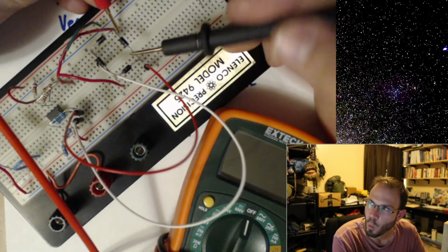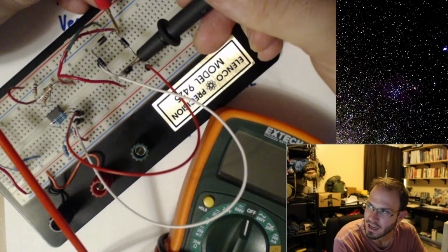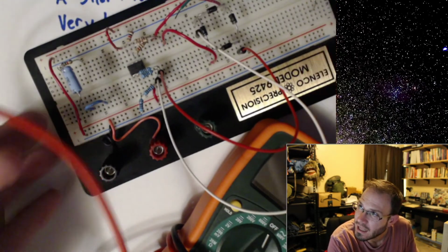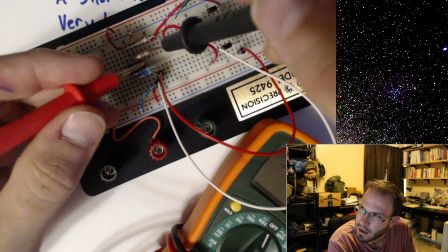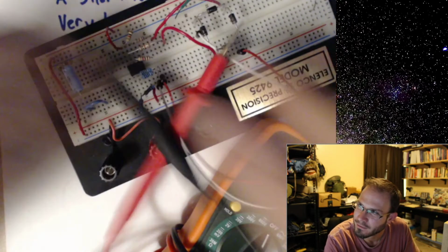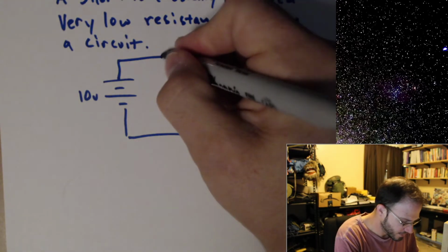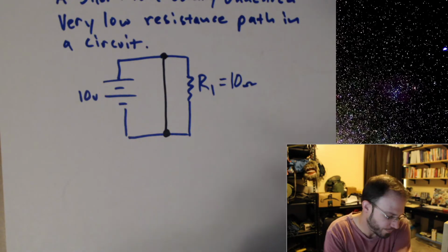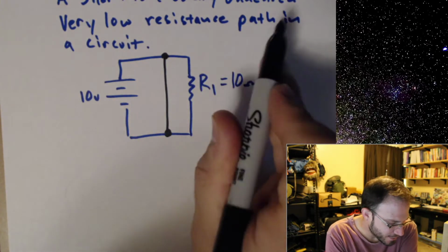I add this wire from one side of a component to another side, and I accidentally touch those wires. And when you have a complicated circuit like something over here, it's not difficult to do. You're probing and you end up moving something, and next thing you know, you end up adding this undesired wire in here. Okay, this undesired very low resistance path.